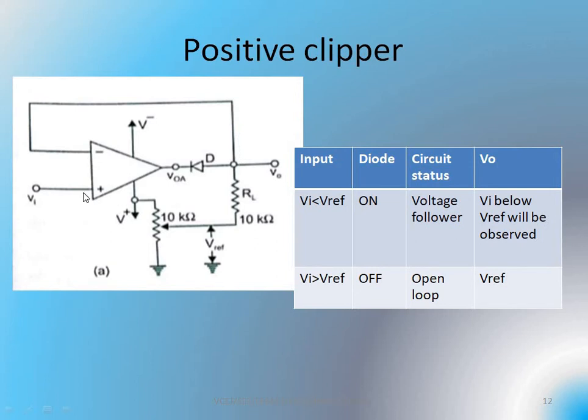What have we applied? We have applied a positive input. That positive input will be entirely carried to the output terminal. Now assume that Vin is greater than the reference value. Here the reference value is a fixed value, 10. Instead of 5, if I provide 15 volts as input, this 15 volts will be applied at this point, so we have 15 at the cathode, whereas the 10 is provided at the anode. Now the cathode operation will dominate the anode operation.